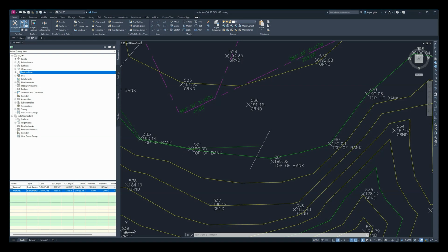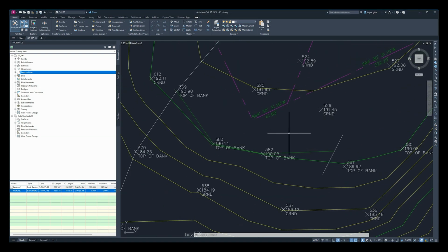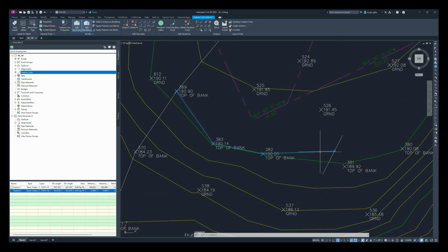Now, another common tool that we would use for editing feature lines is going to be our fillet tool. So back again, once we have this selected, so our contextualization tab is open, we can come here to the center option. It's going to be the 2 endpoints with that line kind of drawn through in the end between our endpoints. So go ahead and select the fillet tool.